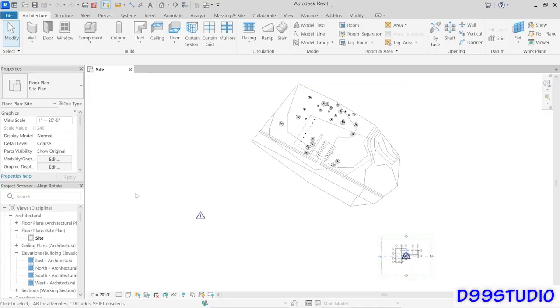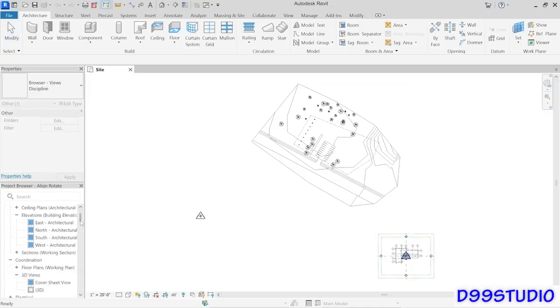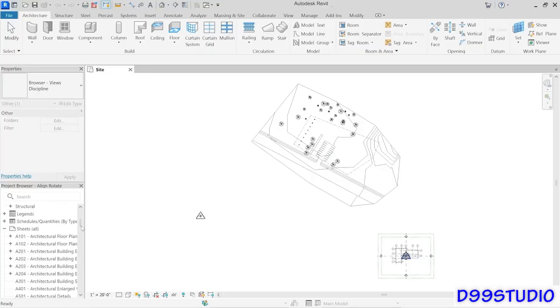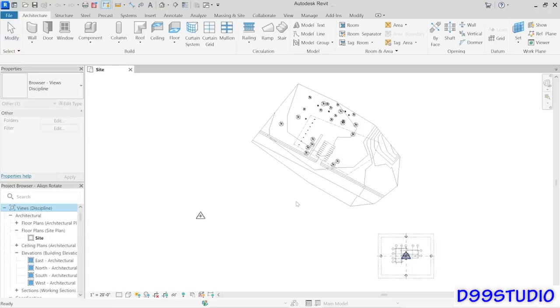And the reason why that's valuable is if you consider all the project setup that we've got in this project template here, we have all these sheets already configured. We have these scope boxes here, the views, everything is already focused on a certain area. Imagine how much work it would be to try and move all of that over to the site. It doesn't make any sense to do it that way. Okay, so what you typically want to do is bring your site information in or your linked information in and then move that to the host location.